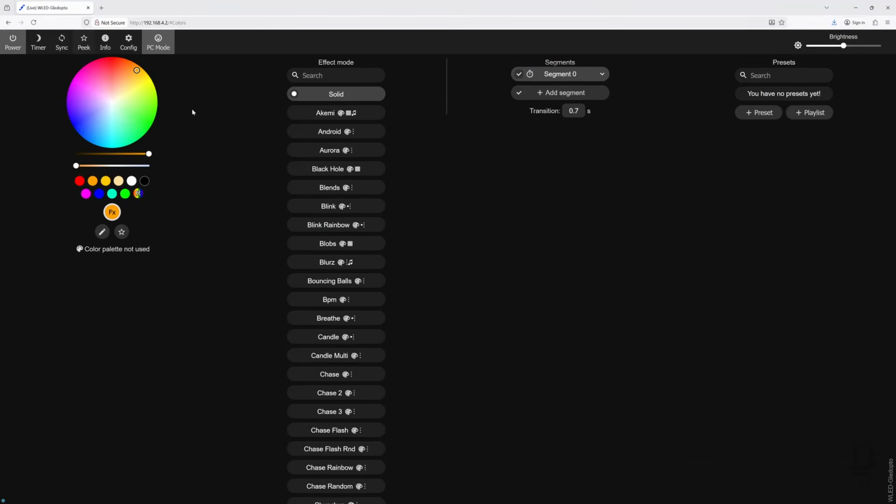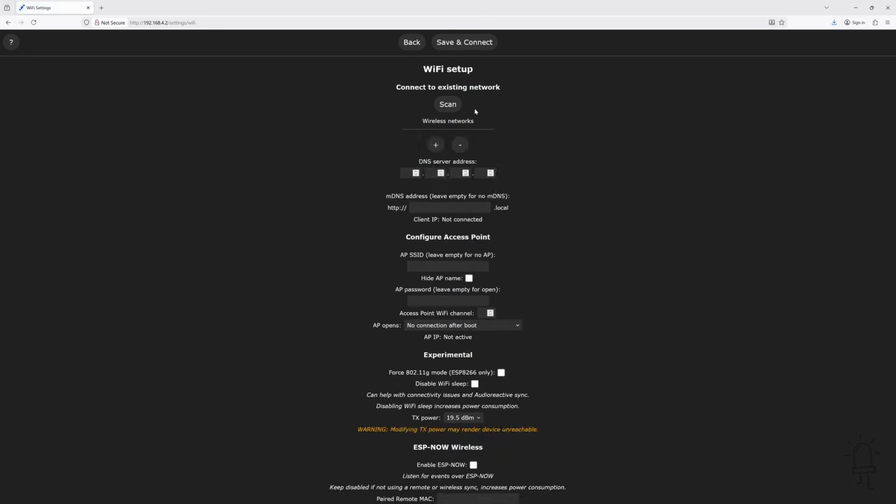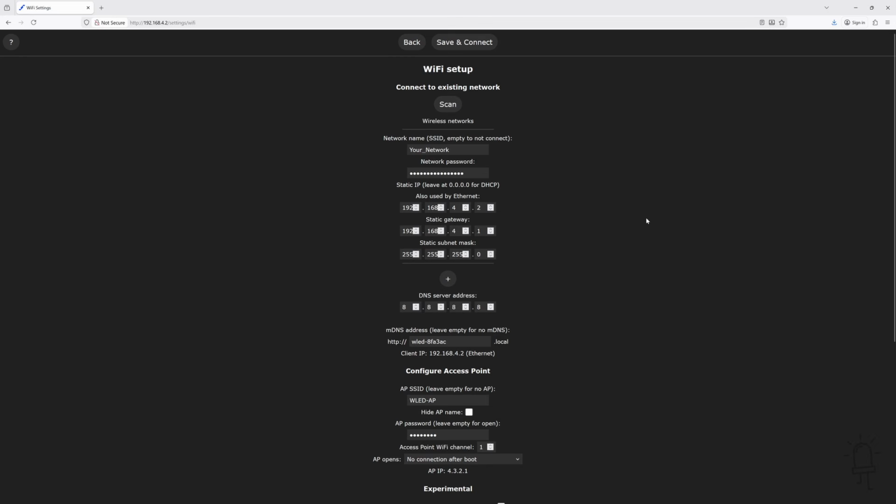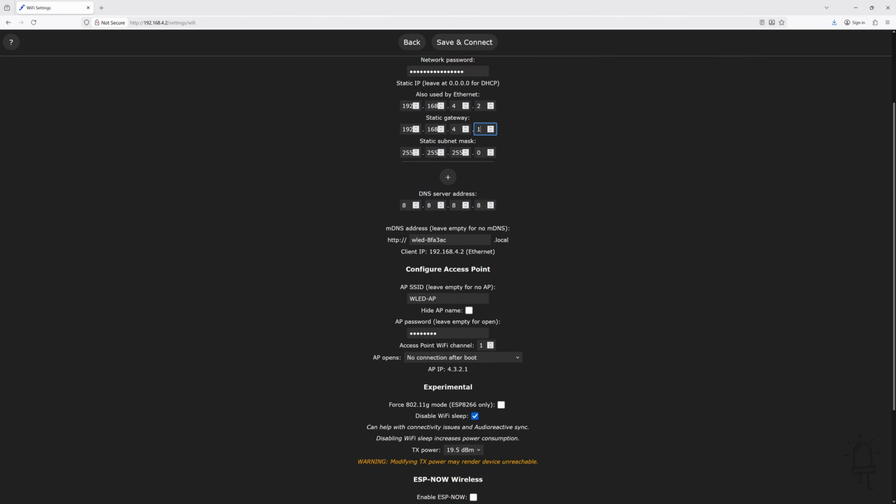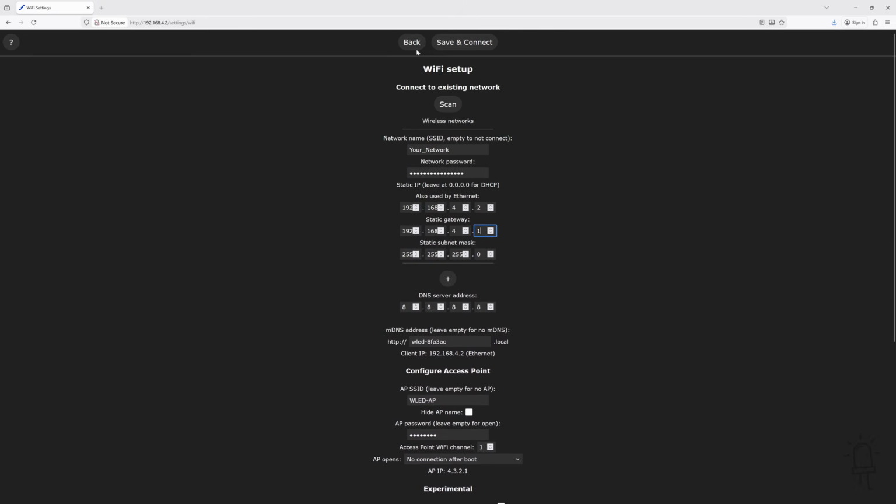Now, in terms of the WLED settings as well, there are a ton of features. So the principal setup is to come into this settings here. This is where I've defined the IP address that I put into Jinx, that I'm targeting this device. The gateway is my PC itself. Like I say, I'm running a local link interface directly between the PC and the ESP32, but if you have them both on the same network, you'd put that as the gateway of your router instead. And you can leave all the other settings there the same.